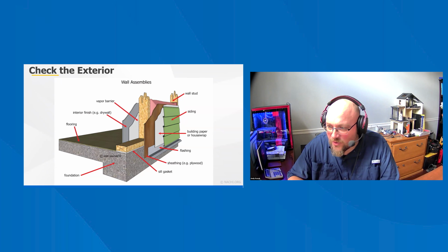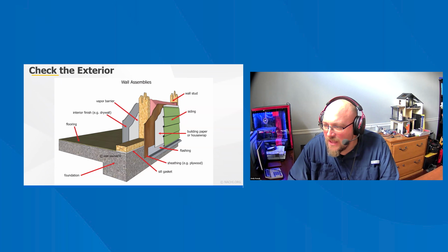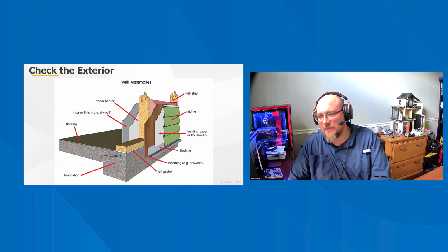Houses in all climates require the following to control moisture. A polyethylene sheet should cover the exposed dirt in houses with crawl space, often called a vapor barrier. The grading around the house should slope away from the foundation. A continuous vapor diffusion retarder with a perm rating of less than 1 should be installed. And a termite shield, sill gasket, or other vapor impermeable membrane on the top of the foundation wall should be installed to prevent moisture from wicking into the wood framing components via capillary action.